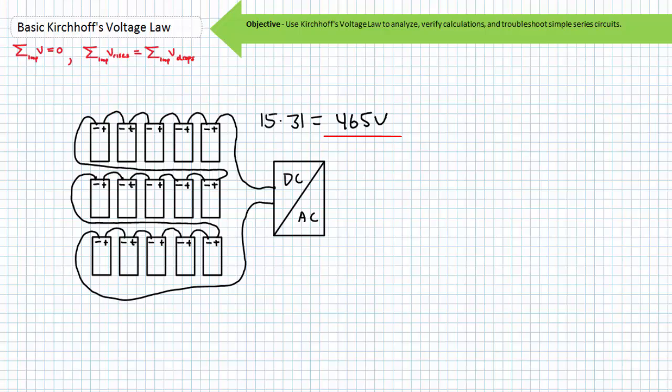465 volts. This is the reason why you want to keep your PV wires out of reach of neighborhood squirrels and tweakers. Provided these PV wires aren't squirrel gnawed or clipped off and sold to a scrap metal vendor, this 465-volt DC input can now be fed to a grid interactive inverter. An inverter, if you recall, is a power electronics device that converts DC to AC.